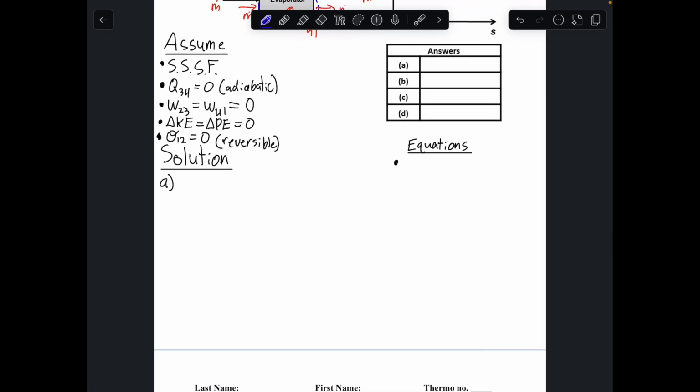So writing that out here, again, we'll see that P1 times V1 is equal to P2 times V2. And so if we want to solve for this V2, we can just move pressure over to the other side here and rearrange to see that V2 is equal to V1 times the ratio of P1 over P2.